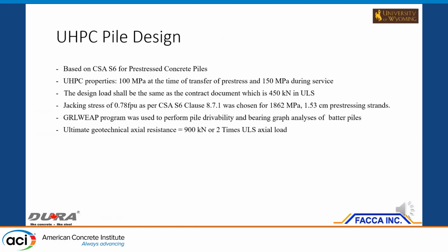Facca provided this information in terms of the initial transfer stress and the expected 28-day strength, as well as the load I mentioned, and they also required us to follow the Canadian code standard, which we met in terms of design. We ran WEAP analysis to make sure that the capacity could be captured, and they followed the protocol to make sure the pile would meet the expectations. So all in all, it was a successful design. I'll pass it back to Philip to give more details. Thank you.